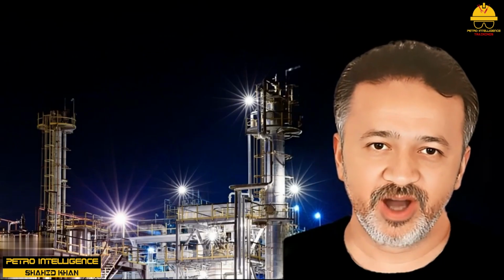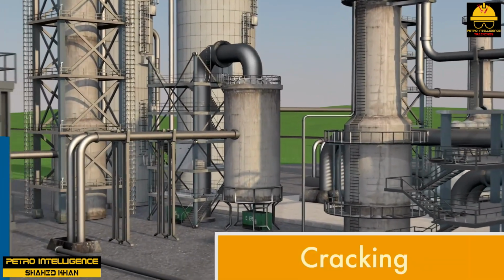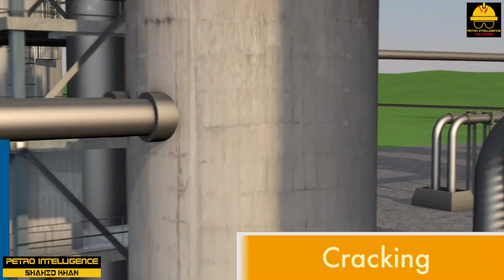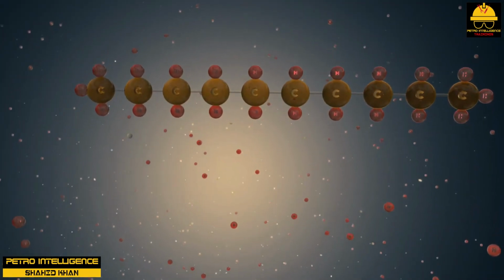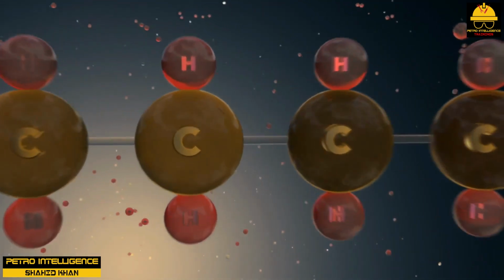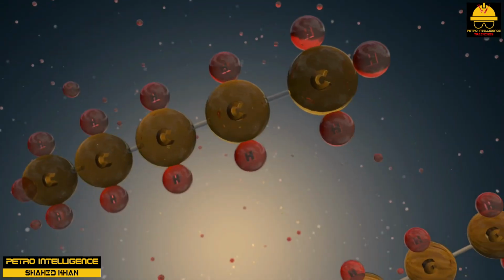Fluid catalytic cracking. Crude oil comes into a refinery and is processed in an atmospheric pipe still. The side stream of the pipe still is rich with light gas oil. Fluid catalytic cracking or cat cracking units take this gas oil and split it into smaller, more useful molecules. During operation, fluid catalytic cracking units use a catalyst regenerator, a fluidized bed reactor, and a fractionation tower.